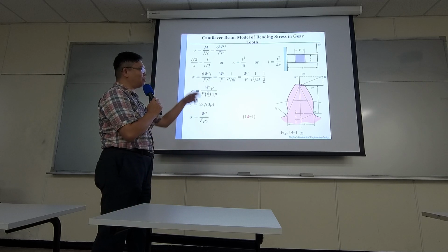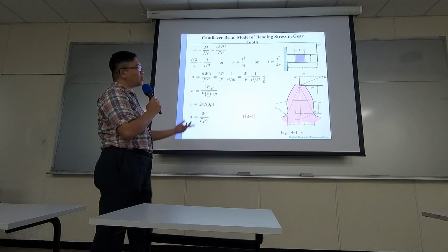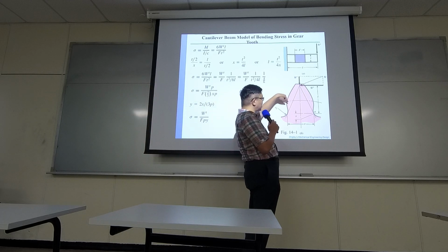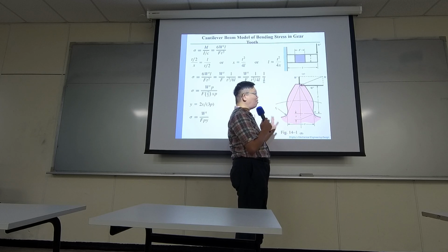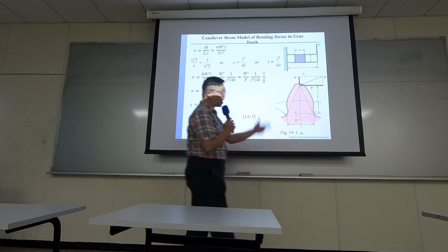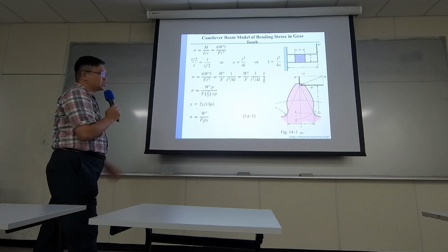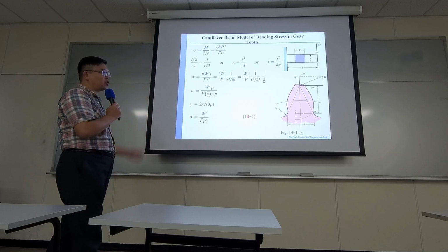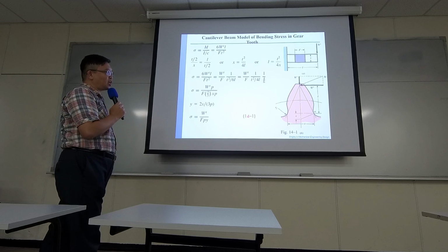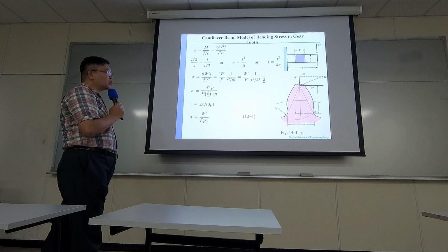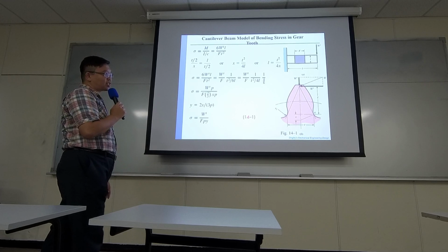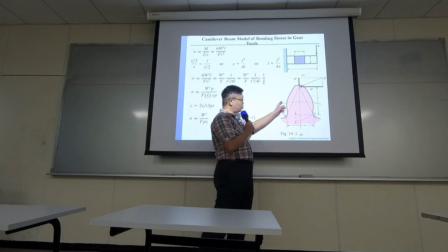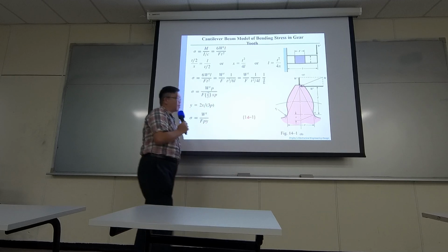So if you truly want to apply some force and then study the stress distribution inside, definitely doable. However, it's not easy because there's no exact equation for this. The geometry can be changing in many different kinds of parameters. So you probably need to use software to estimate the stress concentration, and so on.